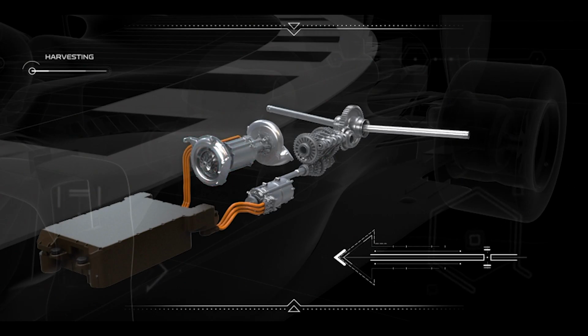And what that is doing is that's when we're going to AMG turbo mode. So we've got the wastegates open, we're not using the turbine to harvest energy, we're actually powering the MGU-H to drive the compressor. So it's very energy hungry, but that's our absolute ultimate performance mode. And we do that right at the start of the straight, as I've said earlier, because that's the part which is the most sensitive to power and lap time.